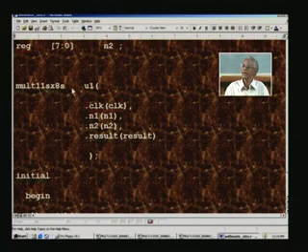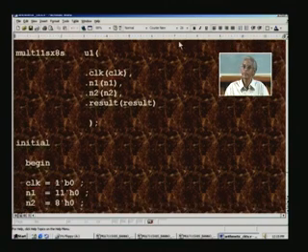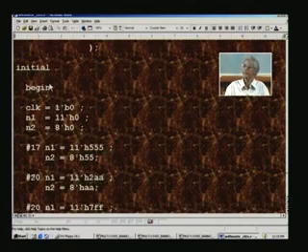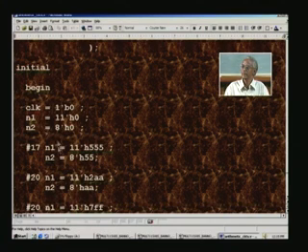In spite of back annotation, it will be the same, because to start with we begin only with this name with the .v extension for the design, and from that we get a back annotated file as we have used here, and because we want the final gate delays incorporated, that is the reason why we use the back annotation there. And we have listed all the ports by name here. And once again, to process the actual test patterns, we need to apply different test pattern inputs here, and we start at 0 time.